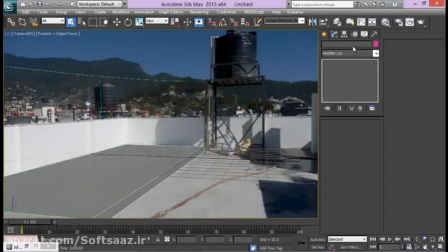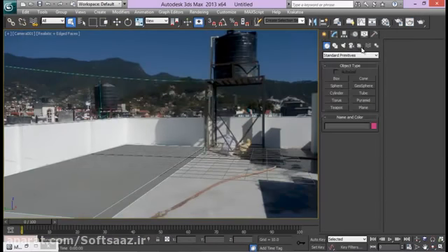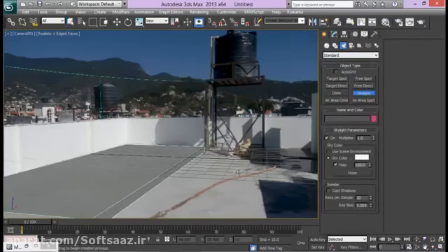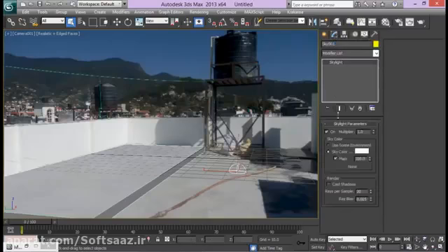So first of all, let us do that. Let us create a simple skylight. Create, and I'm not going to turn on cast shadows right now because that's going to slow my render, or we can also do that and reduce the ray samples to maybe 5.